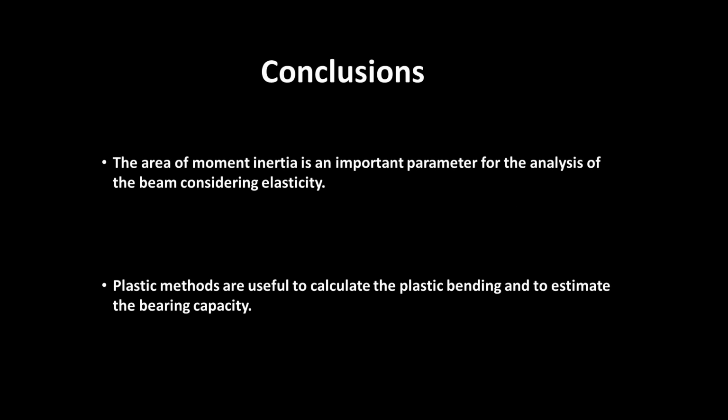From the conclusions of what we learned, the area moment of inertia is an important parameter for the analysis of the beam considering elasticity. If we want to know the collapse load of a beam, plastic methods are useful to calculate the plastic bending and to estimate the bearing capacity.